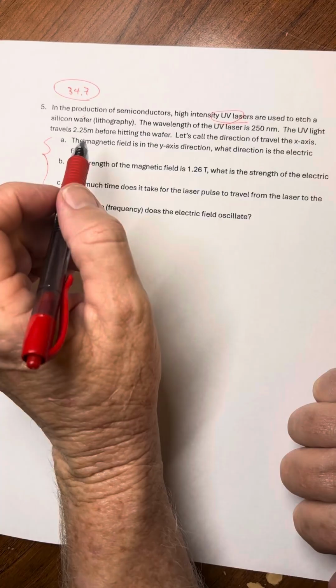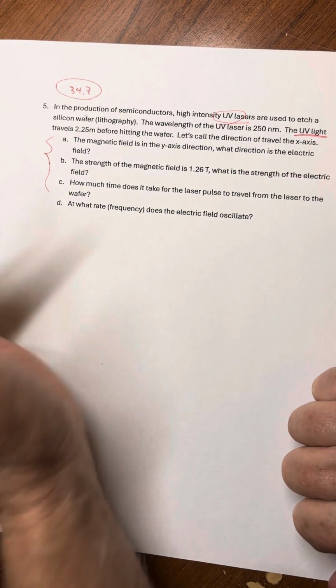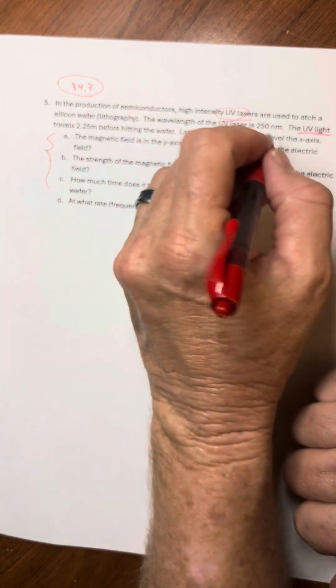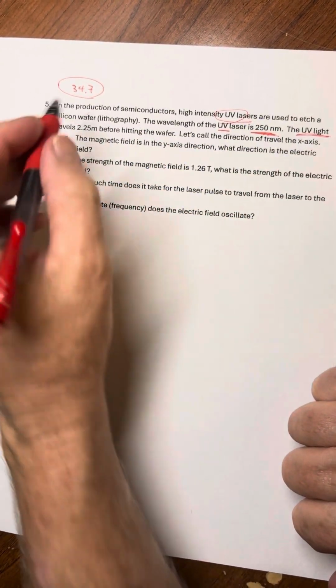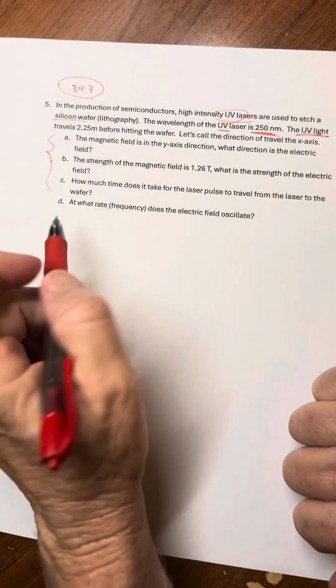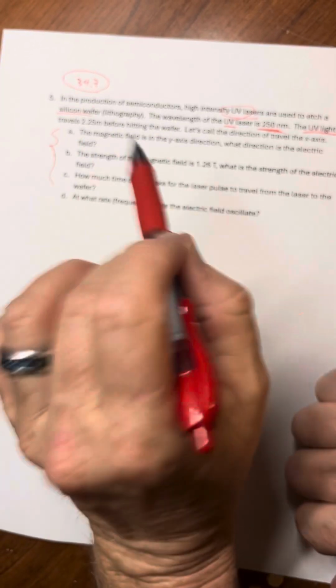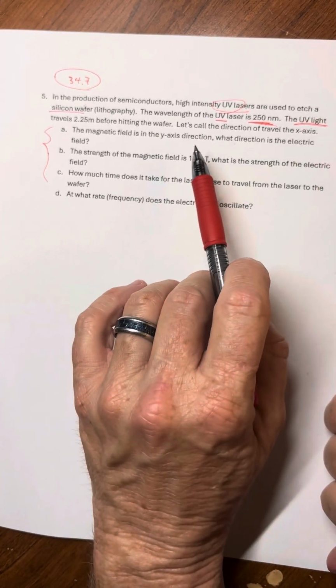And so hopefully right here, regardless of what we're using them for, where it says we have a high intensity ultraviolet laser, this UV light is an electromagnetic wave. Now, in this case, we're going to make it a pretty small wavelength. That's why it's UV. We're going to blast it onto a silicon wafer and dig little channels, so we can make microscopic channels where we're going to then dope it and fill it in. And so we can get something like 1 billion transistors for every square centimeter, some ridiculous amount. And that's how we build all of our semiconductors.